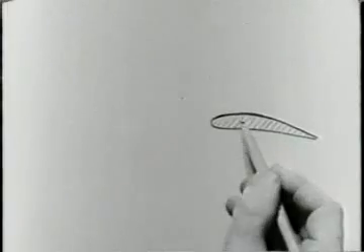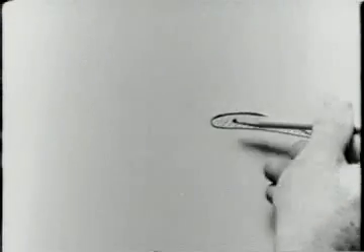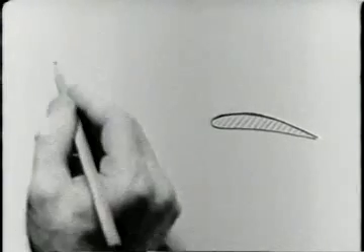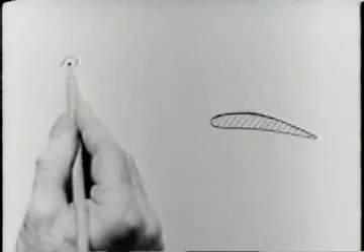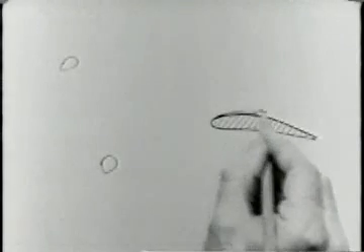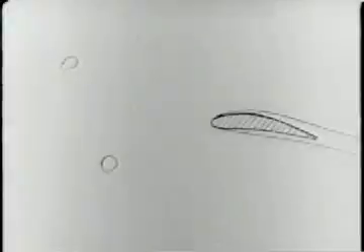Suppose, for example, that an airfoil begins at rest and moves through the fluid. The circulation on all fluid elements is zero to begin with and remains zero, so that the flow remains irrotational everywhere, except in the thin viscous boundary layers where vorticity is produced by viscosity. It is a curious fact that viscosity helps generate lift on an airfoil. Here is an airfoil at rest, with no circulation anywhere.